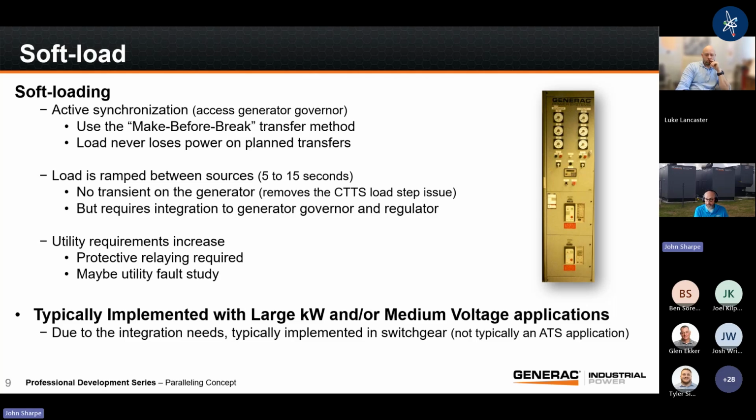When a generator gets a large block load, what you typically see is what we call a transient response. Voltage is going to dip, frequency is going to dip until we can recover voltage and we can recover frequency by getting enough fuel into the engine. Some people don't care for that, especially if you're doing it on a daily basis or weekly basis.